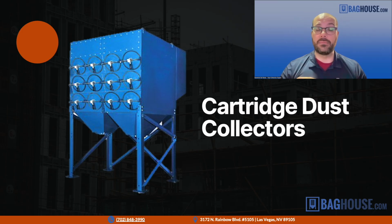Now, if we go back to thinking about the baghouse filters, we discussed the pleated filter elements here. So a common way to get the benefits of a cartridge collector in cement and mining is to take a baghouse and then use these pleated filter elements. These pleated filter elements are a type of cartridge that is designed to retrofit into a baghouse. The media is pleated and jammed onto the filter, so it has more filter area than a bag, but it's not jammed so tightly like the cartridge collector cartridges, where you get a lot of the problems where the dust can't be removed and things like that.